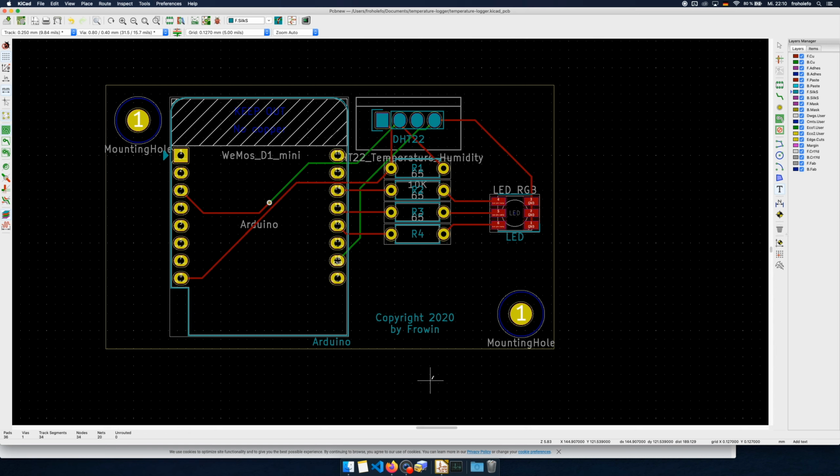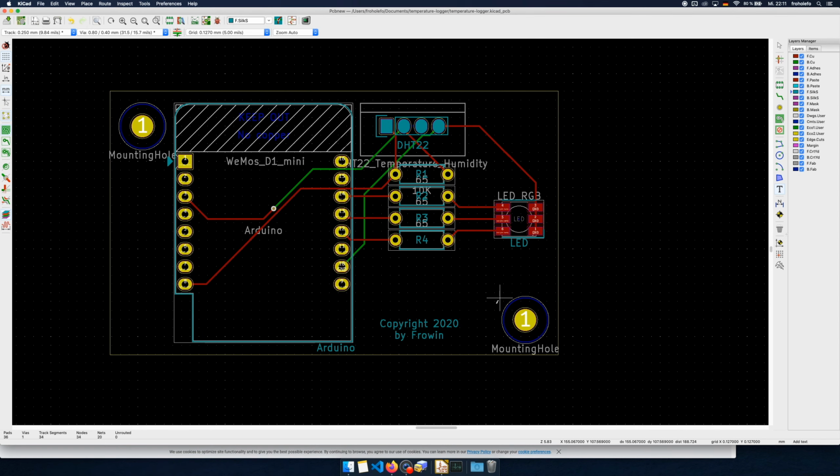Just one good practice is to put so-called, what do you call them, ground planes, maybe, all over the PCB. So now we have these traces, but the rest of the PCB is just empty. There's no copper, and it's common to make everything else a ground plane. For this we go onto the symbol here, add filled zones,